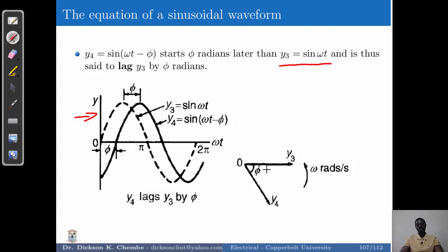And in this case, you'll notice on the phasor diagram that this is lagging. It's below this reference phasor. And this is how you understand that these are important terms, that this phasor diagram is lagging. So you notice that for a lag, the angle is a minus for a phasor that is lagging. And for a phasor that is leading, the angle is a plus.